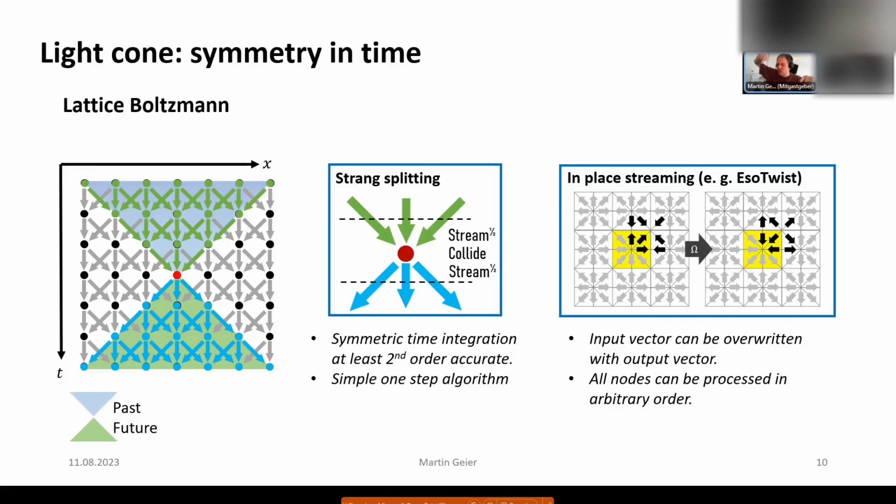You always access neighboring data for doing one finite difference, and you have to access the same data from the other point. So you have to recycle your data. In Lattice Boltzmann, this is not necessary. You have just the distribution going in and the distribution going out. So you can immediately overwrite your input with your output, because you never need to recycle your input.